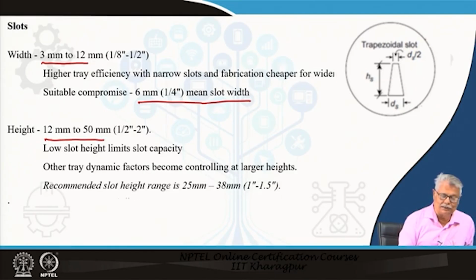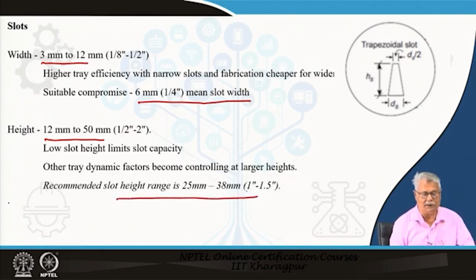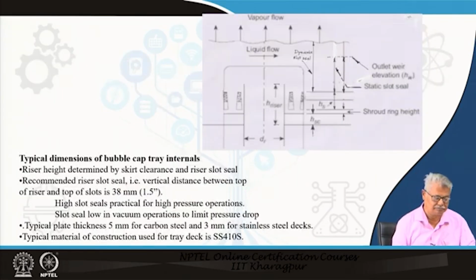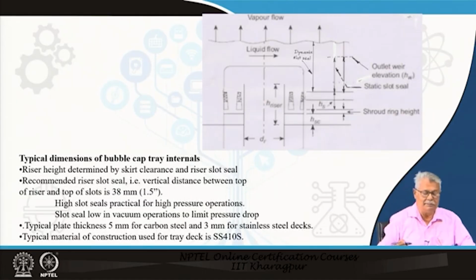The recommended slot height range is 25 to 38 millimeters. 38 millimeters means 1.5 inch. Now, what we have is basically the typical dimensions of the cap tray internals.